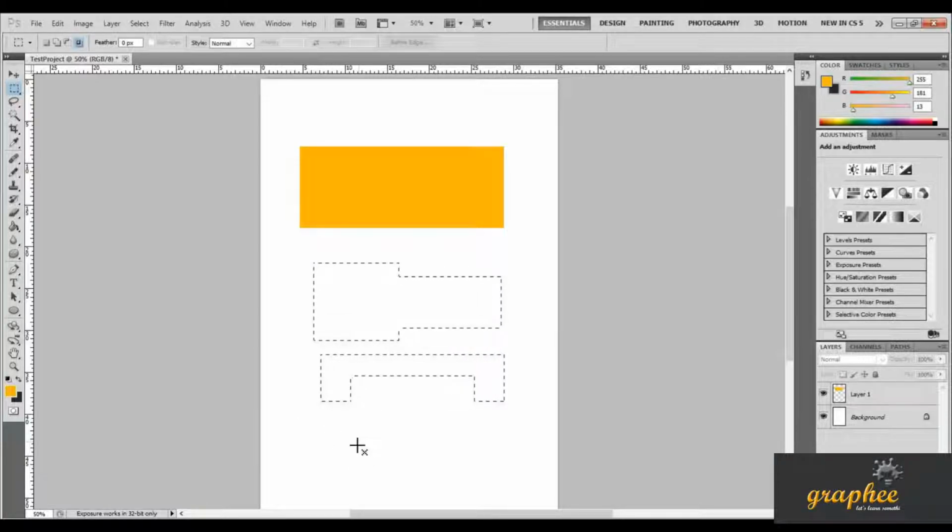The fourth one is intersect. As we all know, in mathematics, intersect means common properties. Let's say I want to have two selections. When I bring selection two onto the existing and previous selection, it will only contain whatever is common inside them. So I'm just going to add another selection here. This will bring only the selected area that is common amongst them.